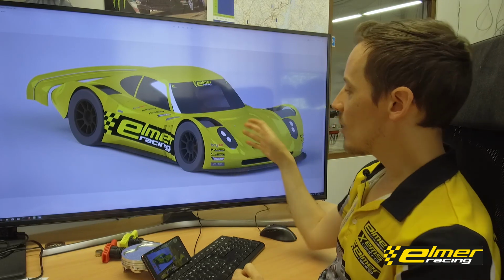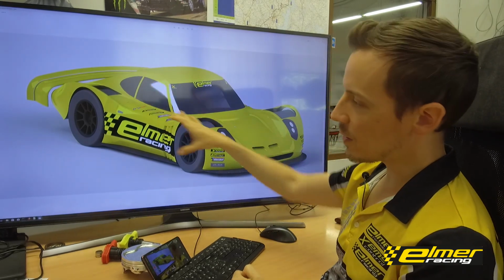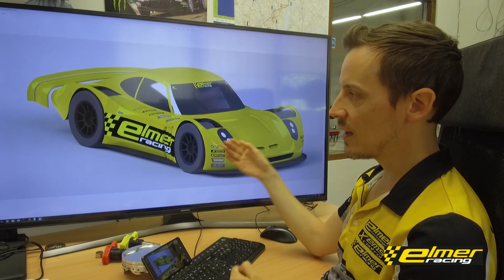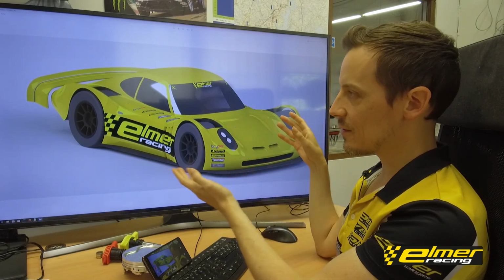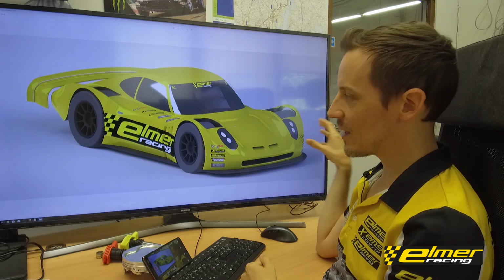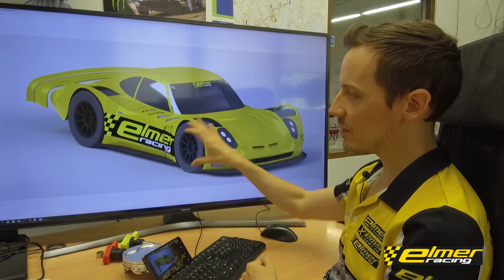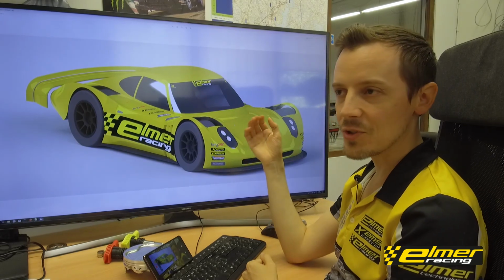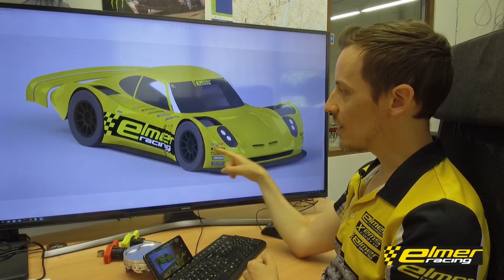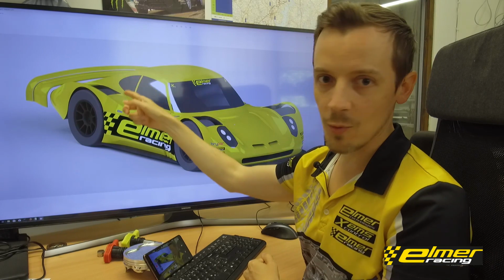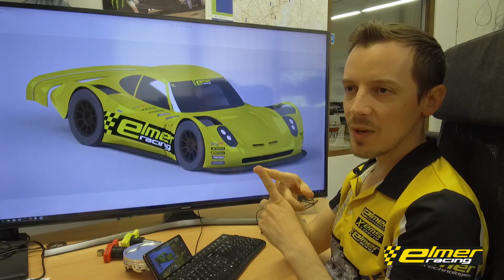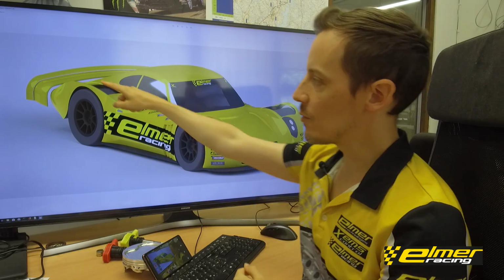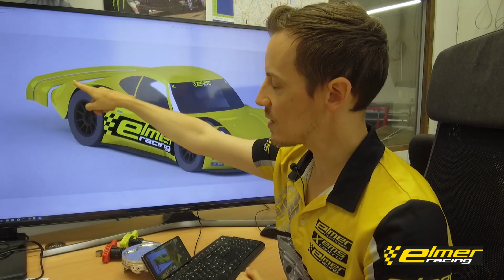So we want to use the whole car as much as possible and not just small individual pieces. Of course, everything is, well, not connected, but the airflow around some part of a vehicle will have an influence on the rest of the vehicle also. So for instance, on our ER8 here, we're definitely using a rear wing, not because the rear wing by itself is a very efficient way of creating downforce, but because with the rear wing we increase the flow velocity.